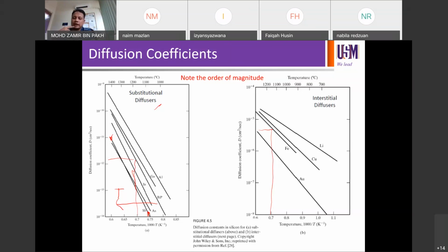So we've seen that these metals will actually be trap states, or in fact, they can also be deep trap states in the band gap. So that will suck your free carriers from the conduction process, right? So you end up not having your carriers for the measurement, for the characterization.